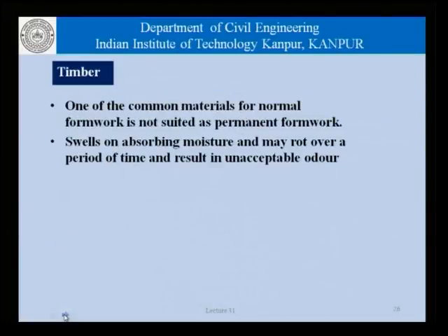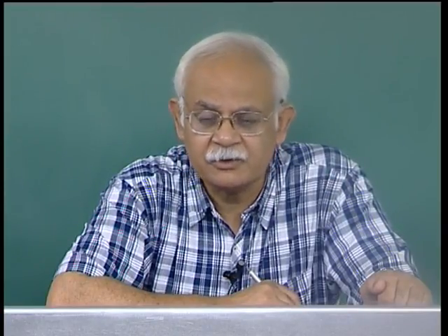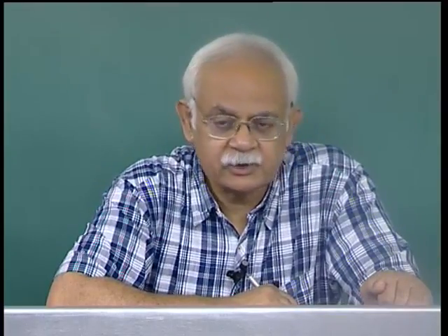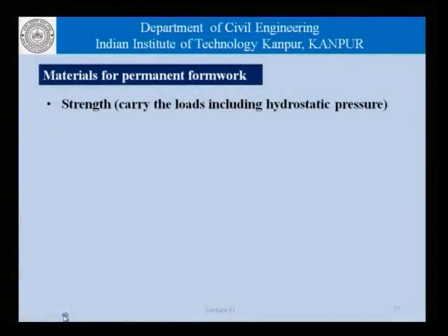Now, let me talk about timber or plywood, which is one of the most common materials used for normal formwork. It is not really suited for permanent formwork construction, because it absorbs water, swells, and may rot over a period of time and result in unacceptable odor. So, these are the kind of problems that normal plywood applications would have if we were to allow them to be part of the concrete structure, and that is why we cannot have them, which gives us a pointer as